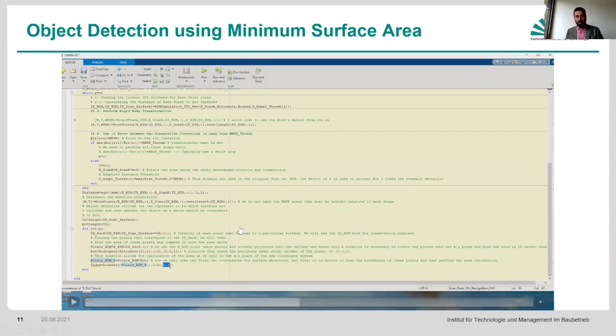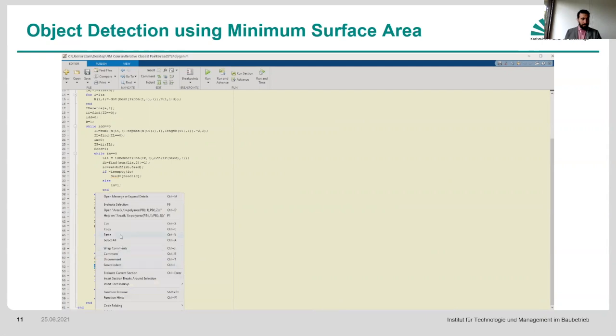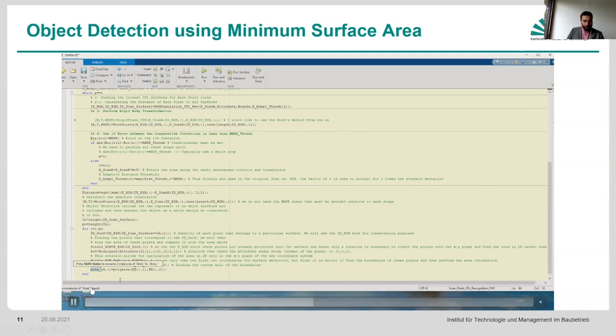Really, the computation necessary to give you the tight boundary is not worth it. So for this example, I put it as 0, and that is sufficient for this type of situation. This is what we call a convex hull when you put it as 0. If it's 0.5, I think that's the modified convex hull, if I'm not mistaken. If it's 1, then it's what we call an alpha shape, where you find holes and whatnot, and you find the critical value. We also get the area from that same function, which is our read STL function.